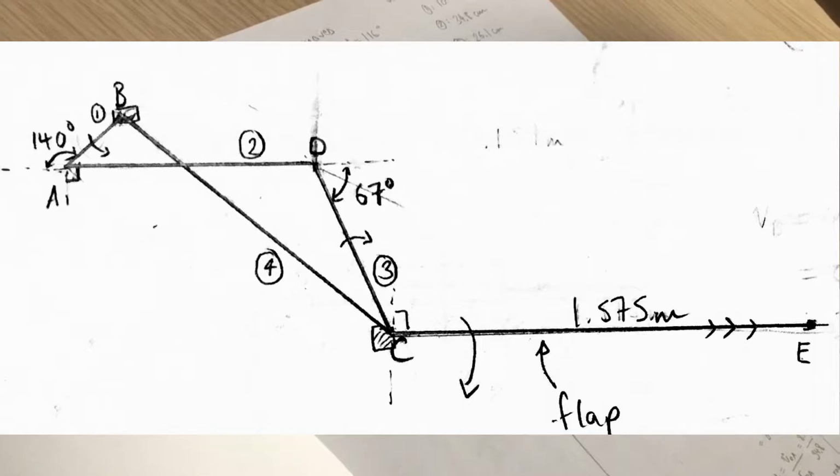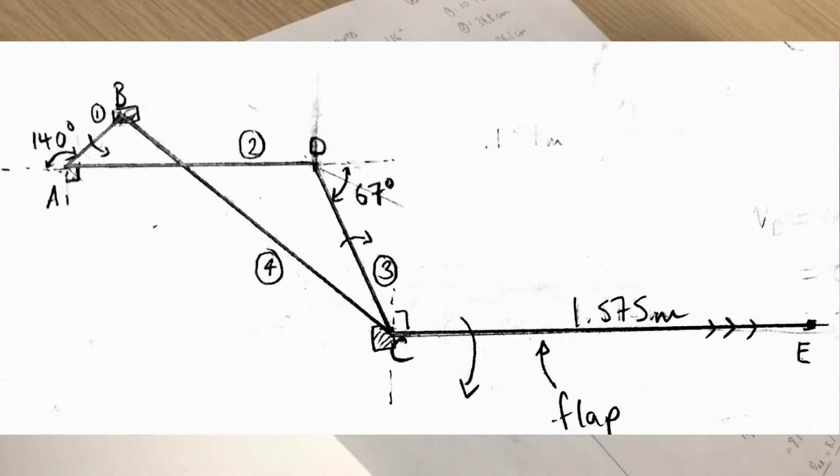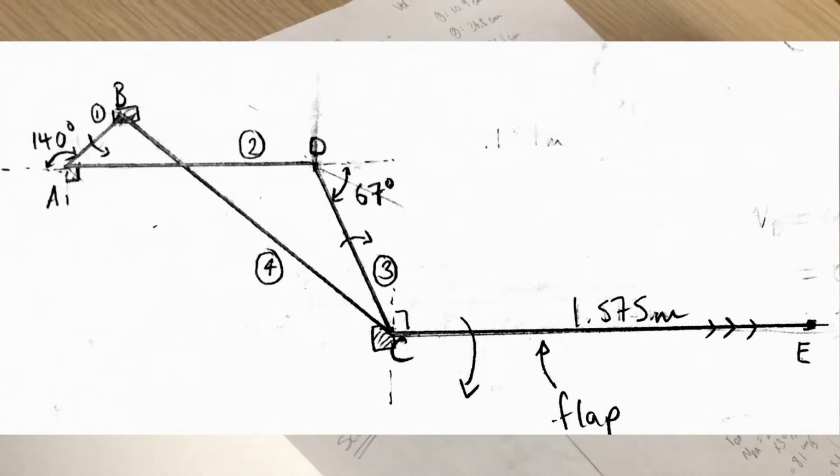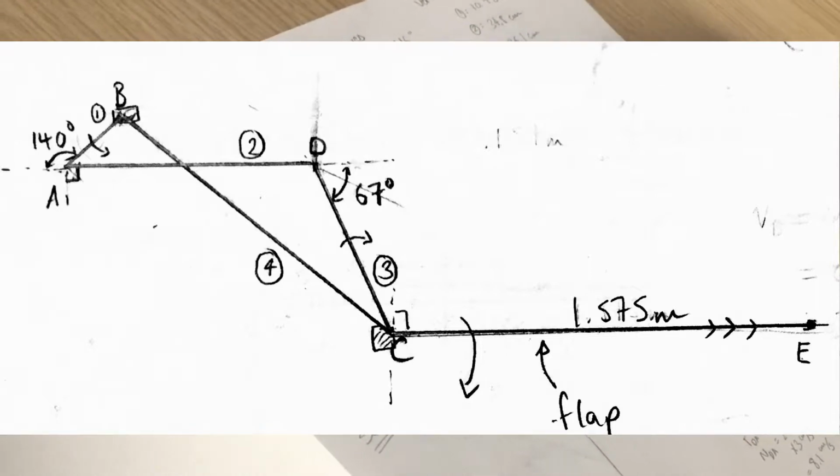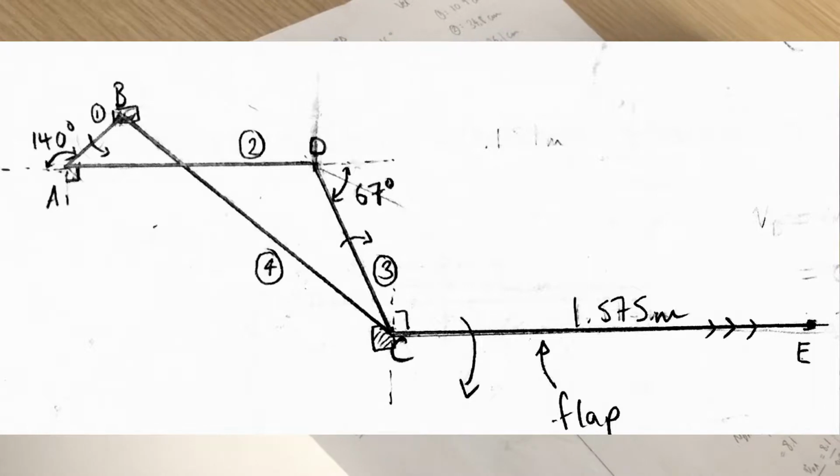The wing flap is an extension of link 3 to the right, however, it is shown only connected to point C for calculation simplification. Link 1 pushes link 2, and as that happens, link 3, or in other terms, the wing flap, pushes down.